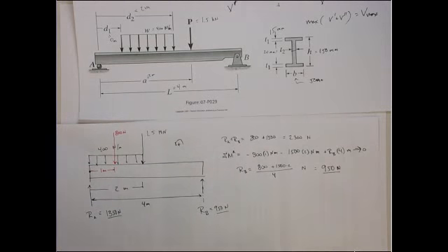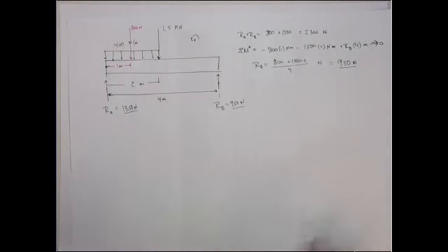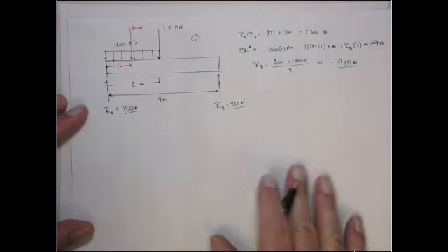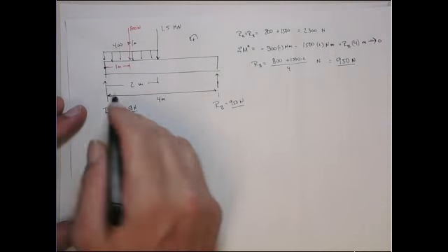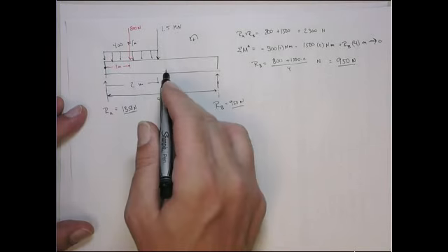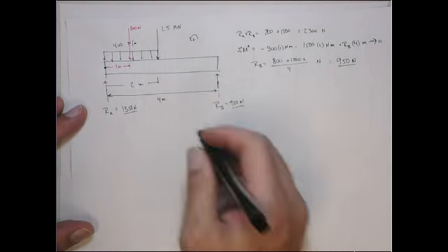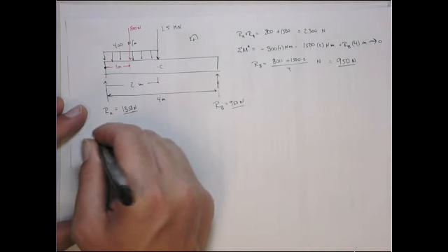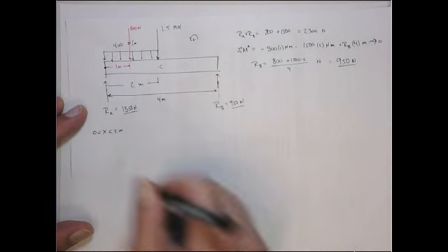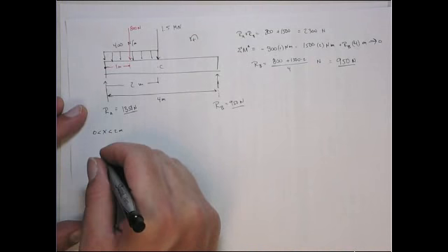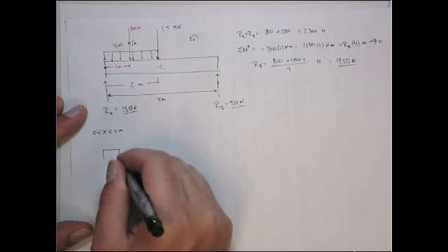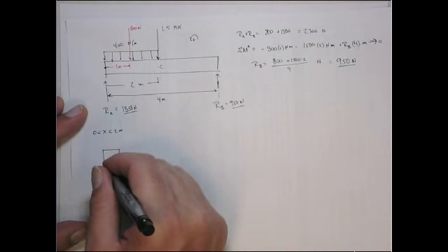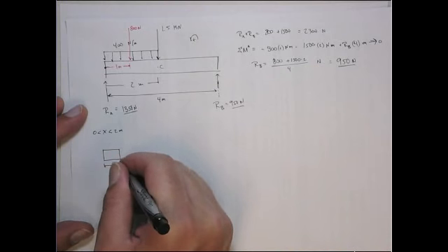Now we can do the shear diagrams. We only need the shear diagrams because this problem is only asking for the transverse shear. Let's first look at it from point A to the mid-span, call this point C. So from x from 0 to 2 meters, what's the picture we have? This distance here is x.